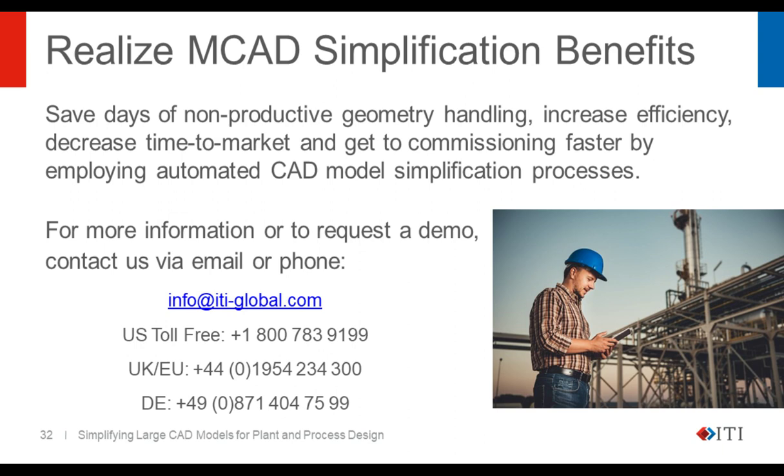Okay. Now, got a very important question here, and this is: can you review the simplified CAD model within CADfix, or do you have to open it with other CAD software? It's all done within CADfix. So CADfix has its own viewing capability. You read the model in, you can assess it, you can specify the tolerances and settings within CADfix, and then when it's finished, you see the final result. We also have an undo button. So if you don't like the simplification, you can press a button, undo it, change the options, and run it again.